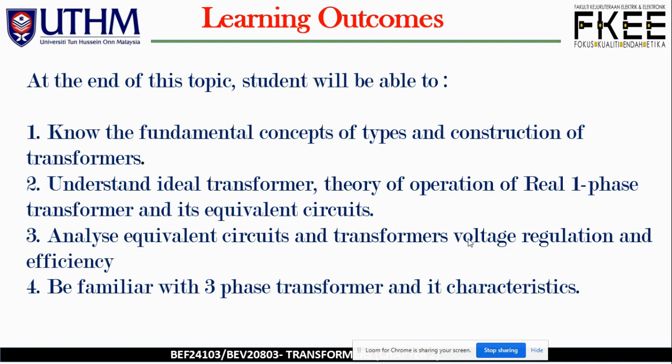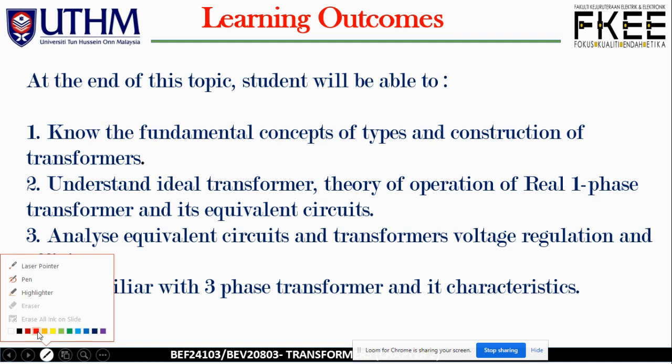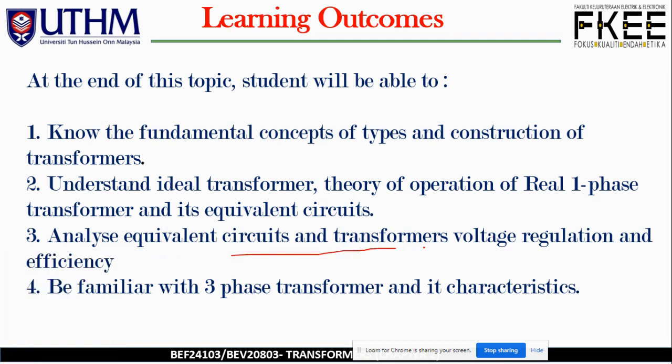Before we jump over to point number 3, where you must be able to analyze equivalent circuit and transformers voltage regulation, the VR over here, and its efficiency.